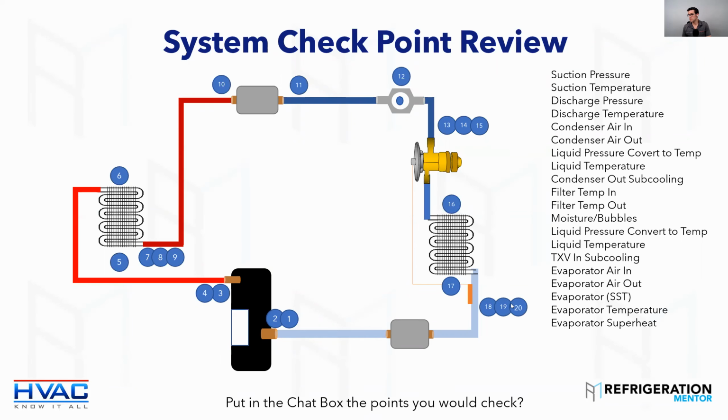Then air in, air out. Superheat. If you have a suction filter dryer, pressure in, pressure out, temperature in, temperature out. Remember, it's way worse. When do you put a suction filter dryer in? The air conditioning we'll talk about that one because there's different applications for it. When would you put one in? After a burnout?